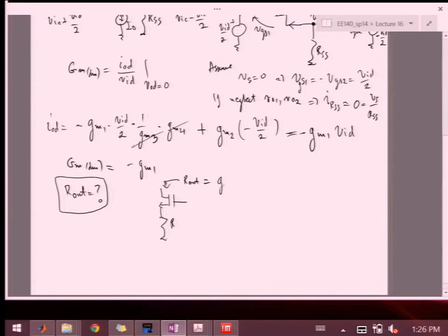Okay, so we said it was, after we cut out many terms that were kind of unnecessary, something like this, right? And that was assuming that this R is actually pretty big. Okay, there were a few other terms that we cannot necessarily neglect. For example, if you look at the real thing, you would have something like RO times 1 plus GMR or something like that. So this one, and there were some other terms, but this one is going to be critical for us in this case over here.